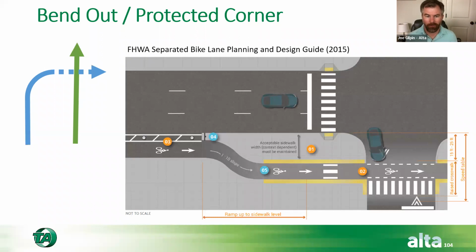And again, if you remember that graphic that we showed a little while ago with the car turning with a greater setback, you're giving more of an opportunity for the driver to bring the bicyclist into their view triangle here. And so the critical length for this, various guides have different dimensions. I believe the next AASHTO guide will probably say 6.5 feet is the minimum setback that qualifies as a setback crossing. That gives you some level of benefit.